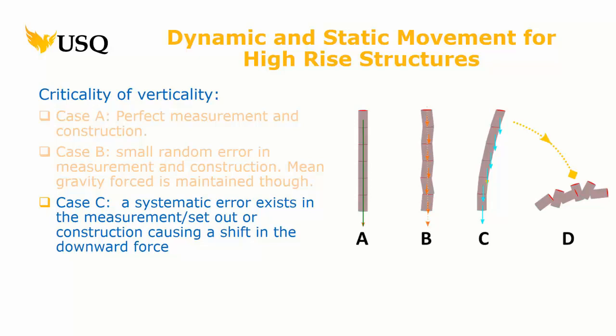So if you're off centre, that's what happens in Jenga. It's exactly the same for a building. So this is why verticality is absolutely a critical thing. And it's something that's difficult for surveyors working in other fields, because you normally concentrate your surveying on horizontal angle precision, distance precision, and mostly the vertical bit you worry about is from the point on the ground to the instrument. And you think, oh, I've got to be right over the point, you know? Or you worry about a vertical angle to determine height, but actual verticality is not something that you use a lot.